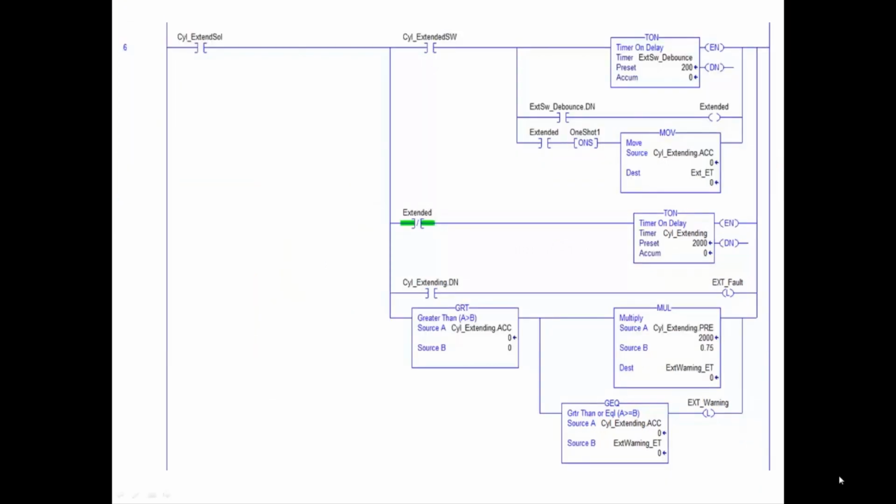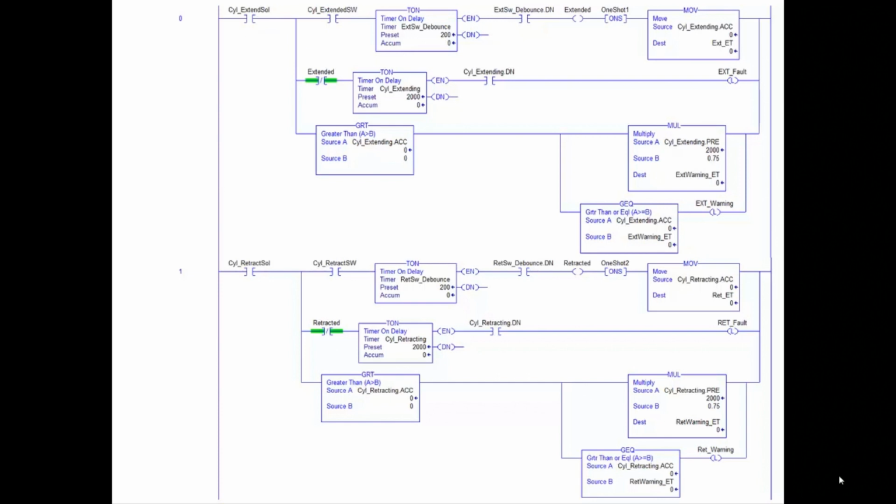If you're not familiar with the sequential instruction programming, this is standard ladder logic format, and it is identical logic to what I just showed you, but it's in the standard format. So if you want to pause the video and study this for a minute, and then maybe go back and look at the other one a couple times, it will come to you. Also, here we have both extend and retract functions together. So these can be inside of one instruction, and typically they would be.